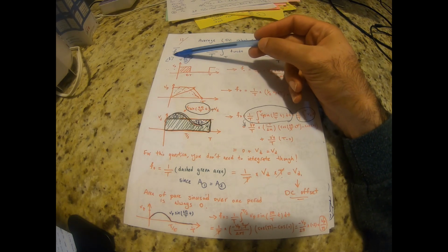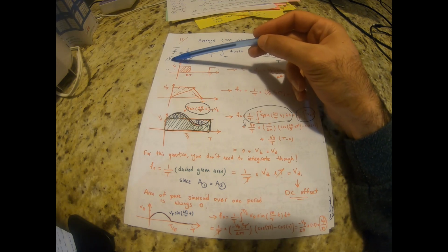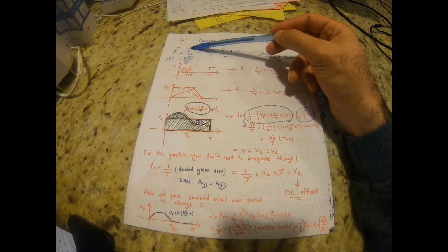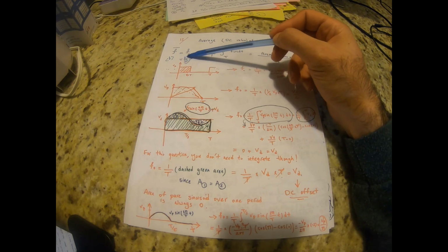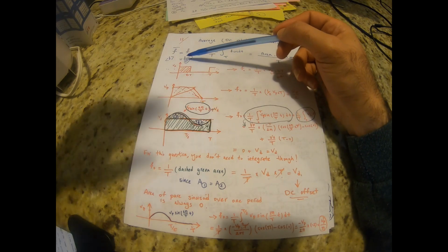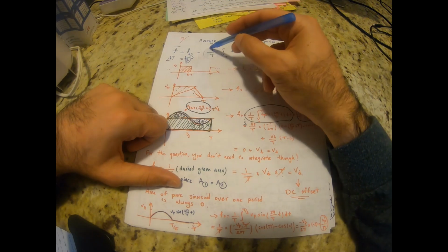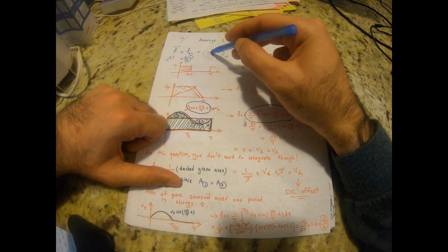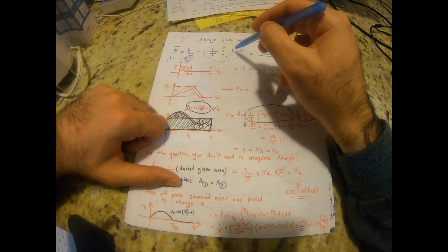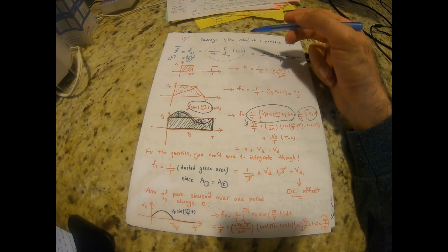Some people show it with a bar on top, or with angled brackets around, or we can also call it the DC component of a signal, or some people show it with F0 because the frequency of DC is 0, right? So what is the mathematical definition for it? It's just 1 over the period times the integral of the function over 1 period. That's basically the definition.